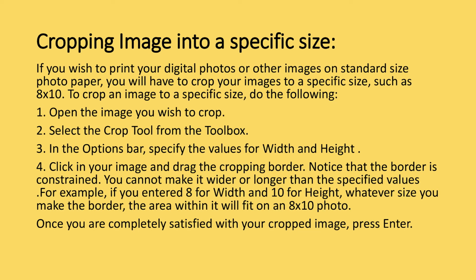Open the image you wish to crop. Select the crop tool from the toolbox. In the option bar, specify the values of the width and height. Click on your image and drag the cropping border. Notice that the border is constrained. You can't make it wider or longer than the specified values.